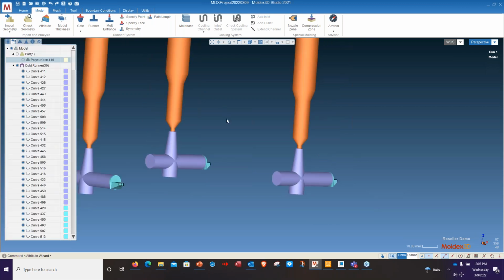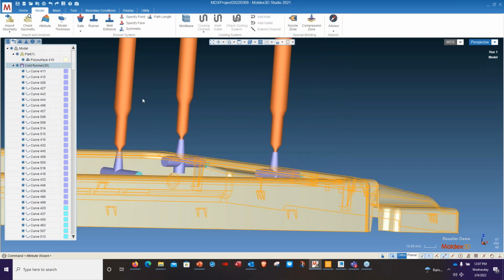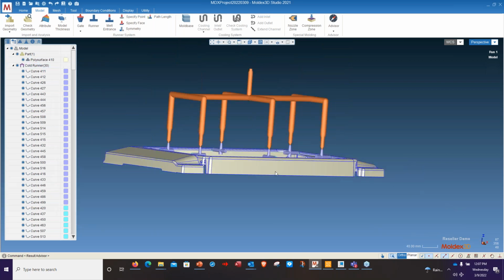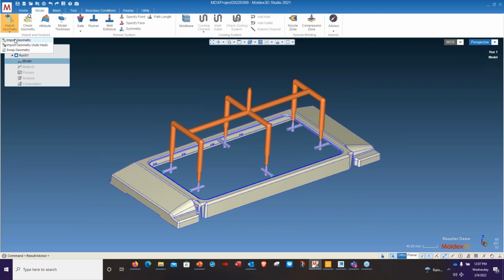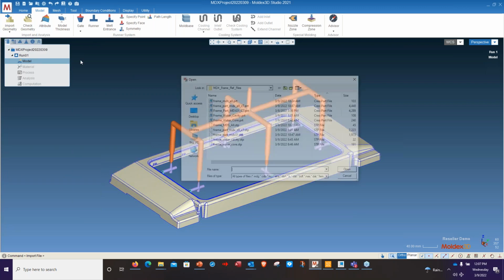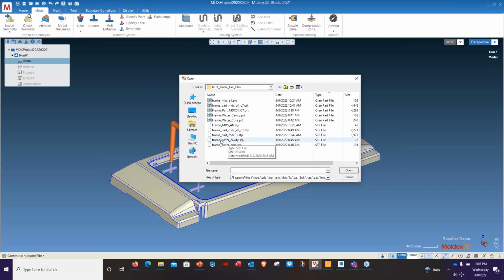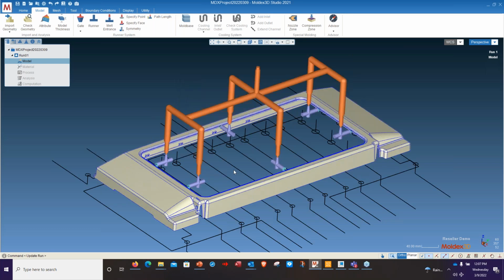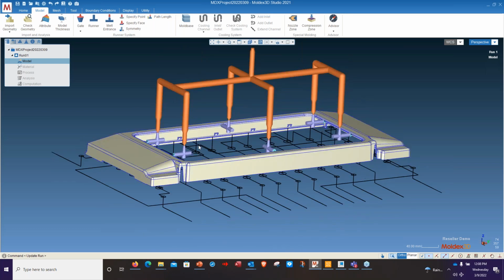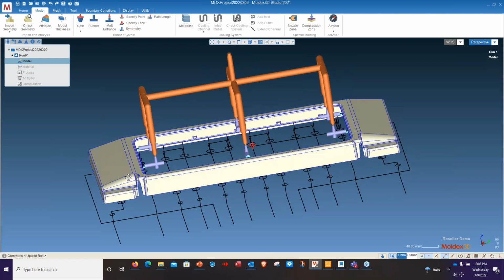Okay, so we now have a part, the cold runner system, the melt delivery system, all attributed. We could go forward now as well as importing other geometry. We're going to import our cooling channels, our water lines. We'll do the core first. Since I imported a step, this imported a little quicker. So we can definitely import step files.